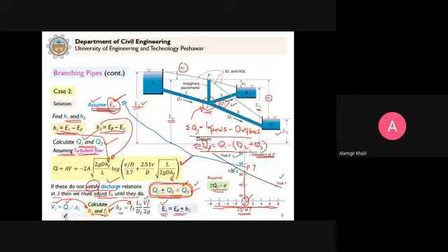So using this diagram, we get help. When we join these trial values by a line, it will not be a straight line, but we assume a straight line. Clear? Then using this figure, we can calculate this value of P by interpolation. So for this value of P, the continuity equation will be satisfied, and we can easily find the final solution to the problem.